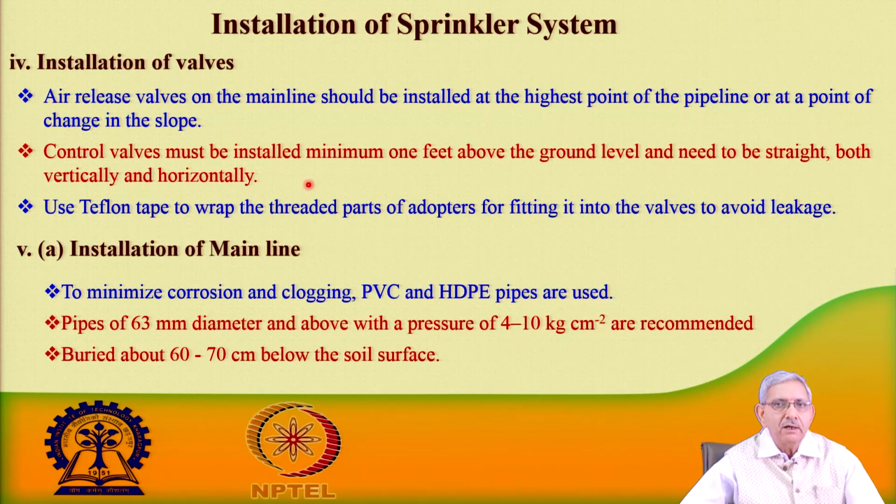These are installed and one should see that they are properly fitted, and then Teflon tape is used to wrap the threaded part of these fittings, so that there is no leakage from the system. The pipeline, whatever the size of the pipeline which we have designed, will be placed in the soil, and these pipelines should have the adequate capacity to withstand the pressure,